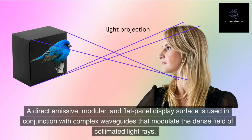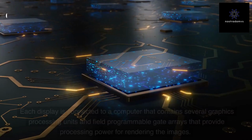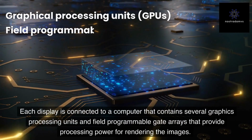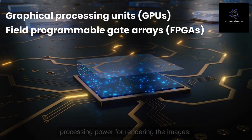A direct emissive, modular, and flat panel display surface is used in conjunction with complex waveguides that modulate the dense field of collimated light rays. Each display is connected to a computer that contains several graphics processing units and field programmable gate arrays that provide processing power for rendering the images.